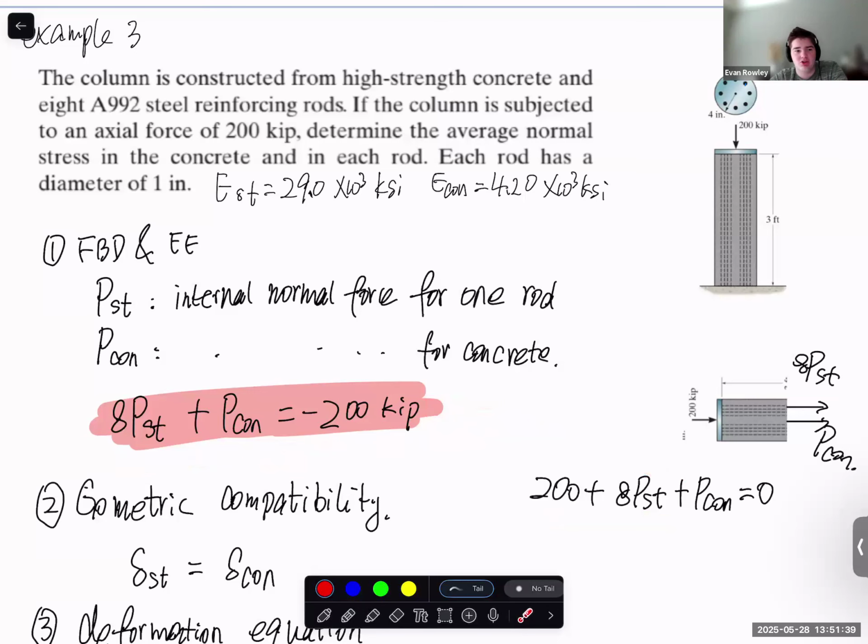In general, for our free body diagrams for this class, should we always just guess that they're going to be in the positive direction and then write our answer negative at the end? Let's combine it with the question in the chat. So why is it negative 200? First, if you see something like this and it's distorted like this, you know that it's in compression. Make sense or not? If I apply a force like this, you know it's in tension, and your equation should be positive. Does that make sense or not?